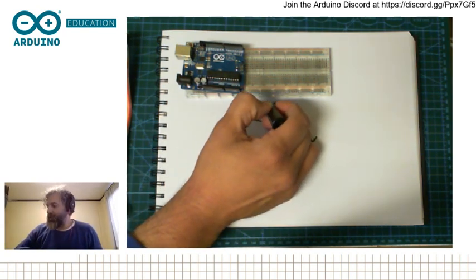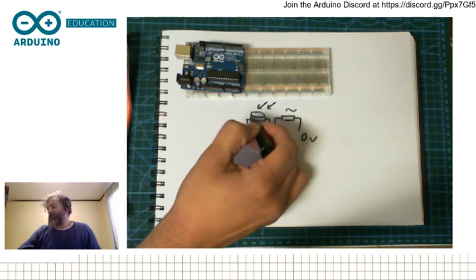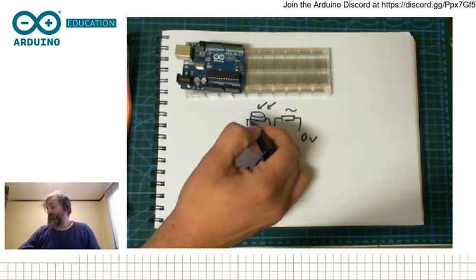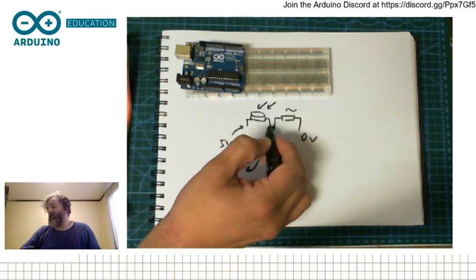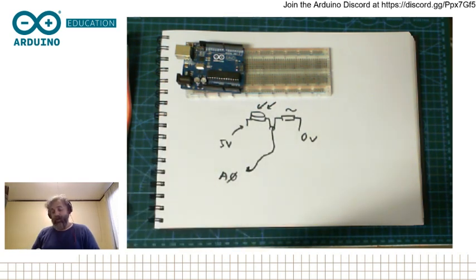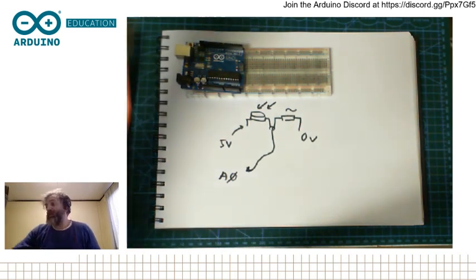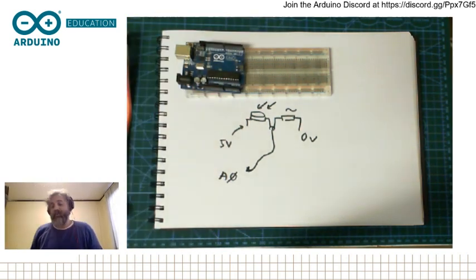So when there is more light coming here, this will change the properties of this material, will change the conductivity, and it will change the amount of current and how the voltage is divided here, and therefore the light will basically change the amount of voltage coming to Arduino, and in that way behave differently.